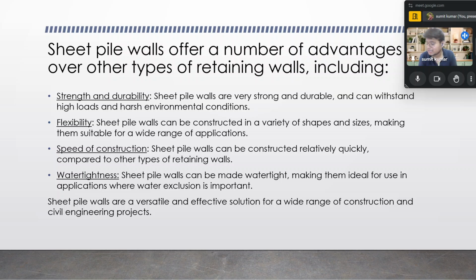Okay, so what I am talking about is strength and durability. When we use the sheet pile wall, its strength will be relatively higher compared to any other condition, and it has flexibility so that we can move it from here to there. They can be installed at any place in very little time, it is a very speedy way to get installed as well as removed whenever needed, and it can also stop water from flowing through them. So these are some aspects which the sheet pile wall fulfills.